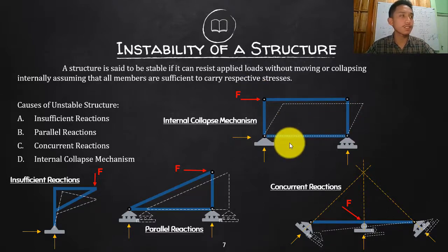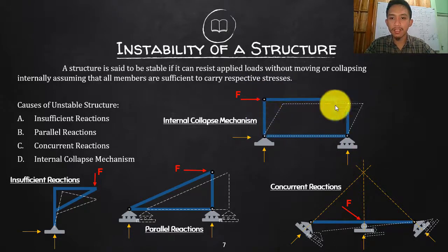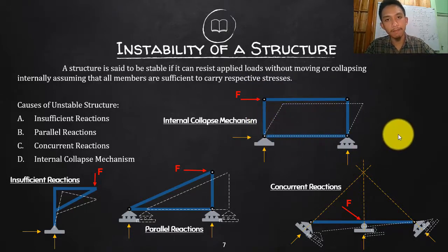That is the actual scenario on buildings. There is no inclined post connecting it to the beams, because that is designed as a frame. So a frame will resist a moment. So even if there is no lateral bracing here, if it is designed to resist a moment, then it will stand. Since here we assume that this is a truss, which is pin connected, it will collapse that way. Okay.